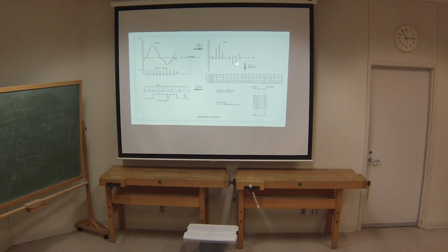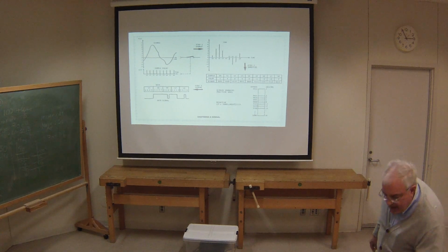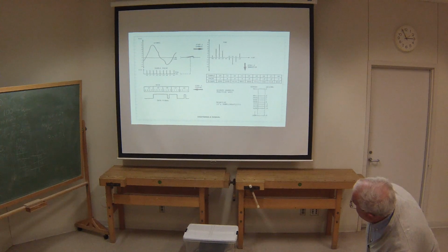So for example, here we have negative going pulses, and to show a negative number in binary, we have to do something like gray code or two's complement. Yeah, that's what you use there, two's complement, right? Yes, this is two's complement, exactly. Oh, there it is, it says that. And this, if it was compact disc or any kind of PCM audio, would also be encoded in NRZI, which is called non-return to zero inverted, and so on and so forth. But that's kind of beyond what we're talking about today.